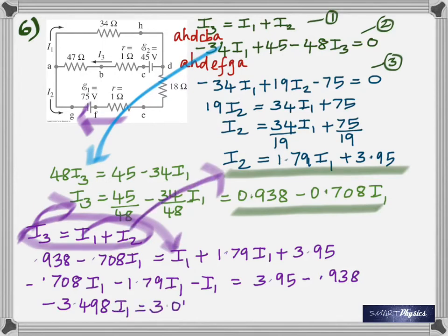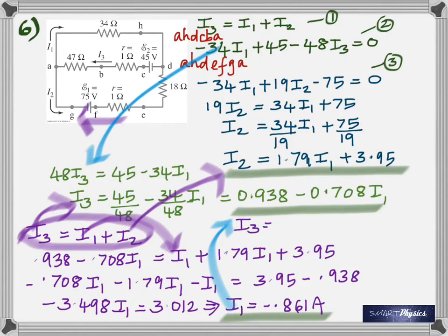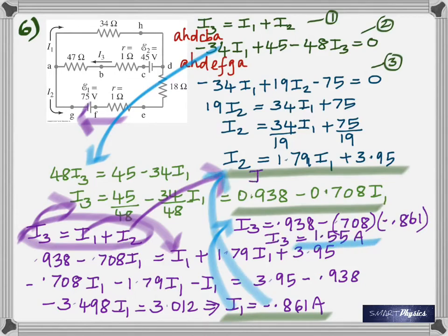All right, I've carefully shown you what I've done. And then I get the value for I1, which I substitute back into that equation to find I3. Kind of running out of space, and then get I3. Once you get I3, put it back into one of those equations and get I2. And you can solve using matrices or use simultaneous elimination method or whatever, but getting the equations is the most important part.